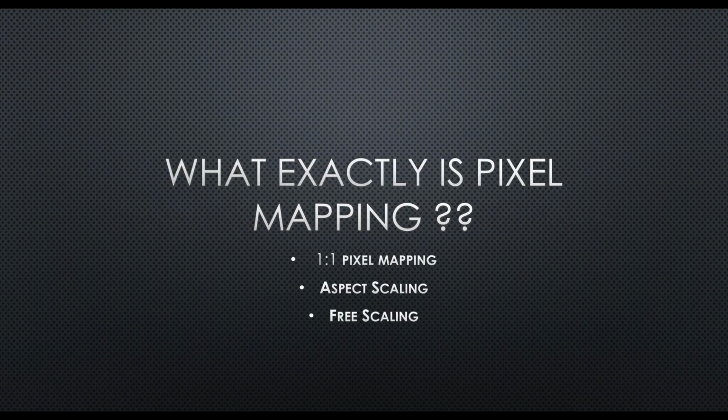When we're looking at pixel mapping, let's focus on that first. It's going to be a one-to-one pixel map. So if your LED screen is, let's say, 1920 pixels wide by 1080 pixels tall, and you're supplying a 1920 by 1080 signal, then it will be pixel mapped. If you are altering that resolution, let's say your input resolution is 1280 by 720 and your LED screen is still 1920 by 1080, you are going to have to scale that.